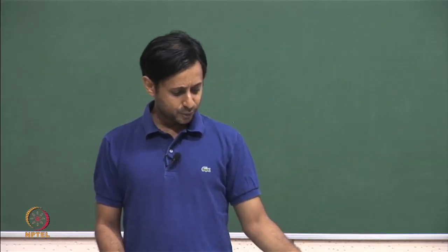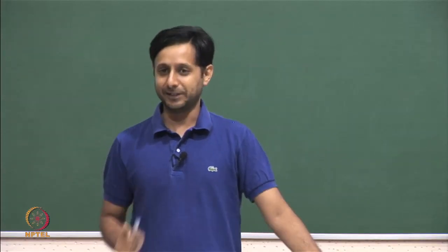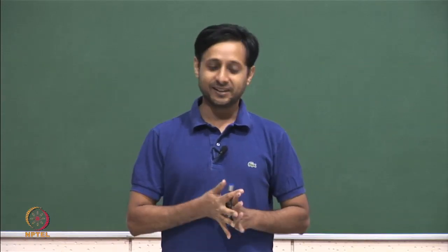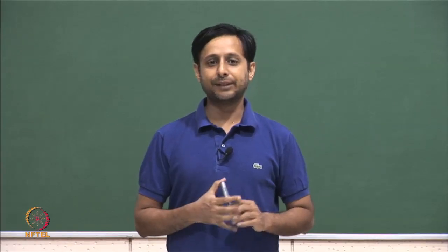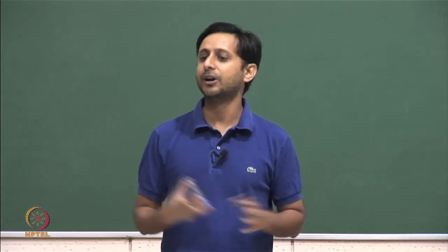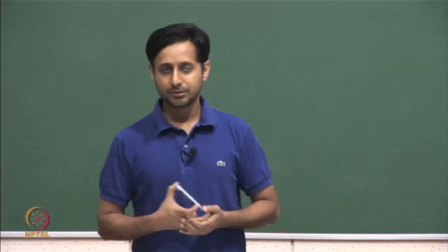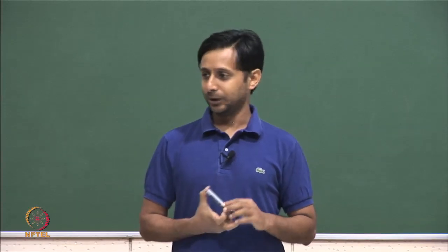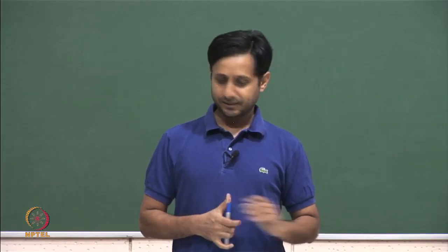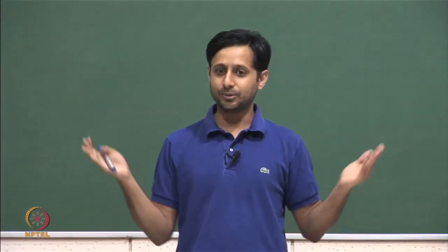All right. Now, of course, this is all fine, but the technique that you learnt in circuit theory is actually the better one. This will work out to some extent, but whenever you try to make complicated polynomials, higher order systems, anything more than third order, things are not really going to work out very smoothly if you try to do it with the Tow-Thomas biquad. But otherwise the Tow-Thomas biquad is a very nice approach, because cleanly you get the whole system in one shot.